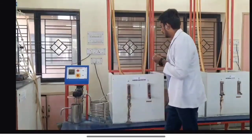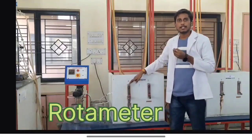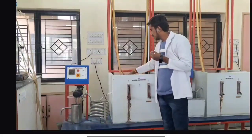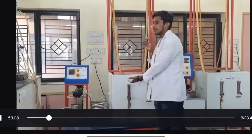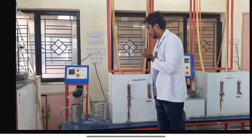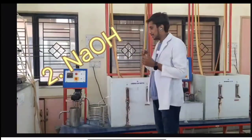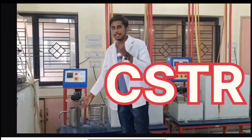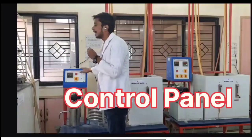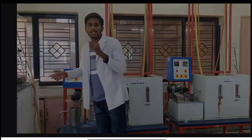So let me introduce you to the various components of our experiment. This is the flow rate tank. Here are the two rotameters which control the flow rate, and here is the tank. Here is the reactant tank in which we are using the components of our experiment, one is ethyl acetate and one is NaOH. Here there is a plug flow reactor, here is a CSTR reactor. This is a controller through which we can operate. We can control the speed of the agitator and also switch it on and off. This is the outlet from which we will take the sample.